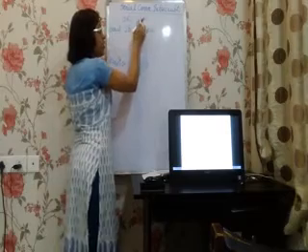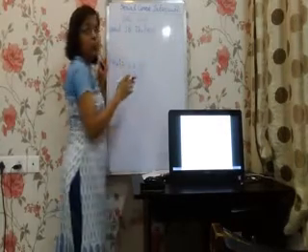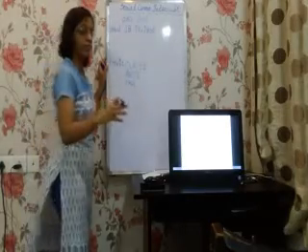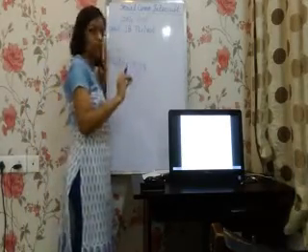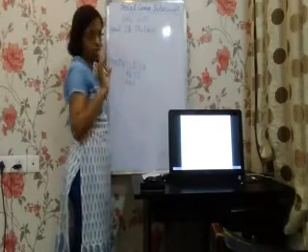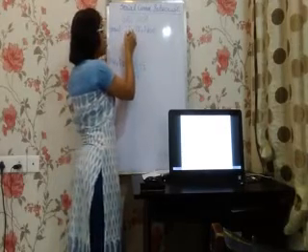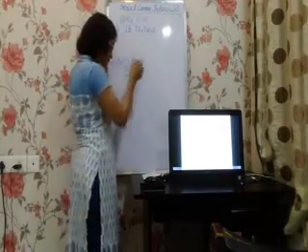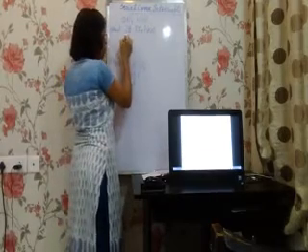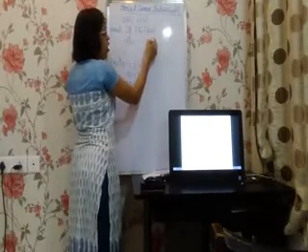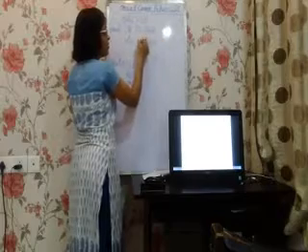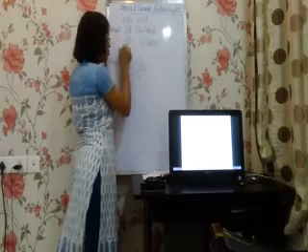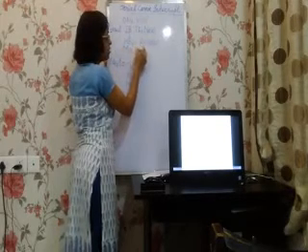If this TI flag is 0, 8051 is not working as a transmitter, we presume that it is working as a receiver. Now this is a bit contradictory, but this is what we have to assume whenever we do serial communication programming. So this means 8051 is working as a receiver. When 8051 works as a receiver, what we need to do? We need to put the value already received in SBUF into a safe place. So move A, SBUF. Okay, and I put it at port 2.